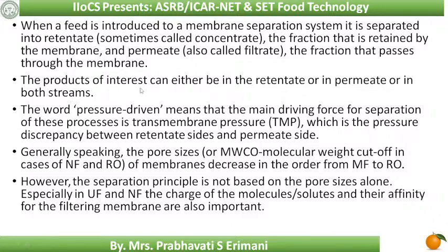So the product of interest can be either in the retentate or in the permeate; we may be interested in both streams. Pressure driven means that the main driving force of separation is the transmembrane pressure, which is the pressure difference between the retentate side and the permeate side.